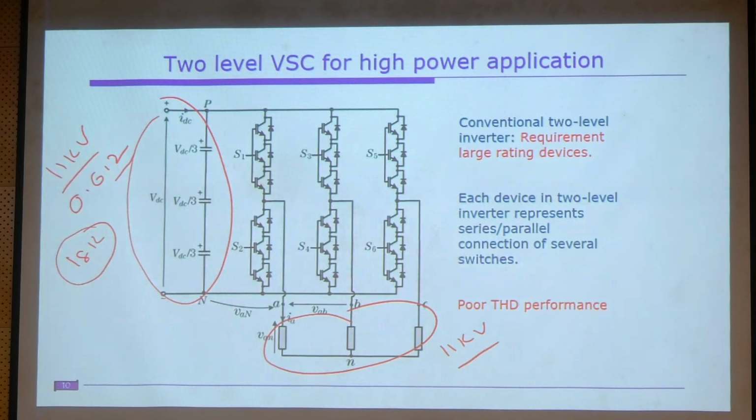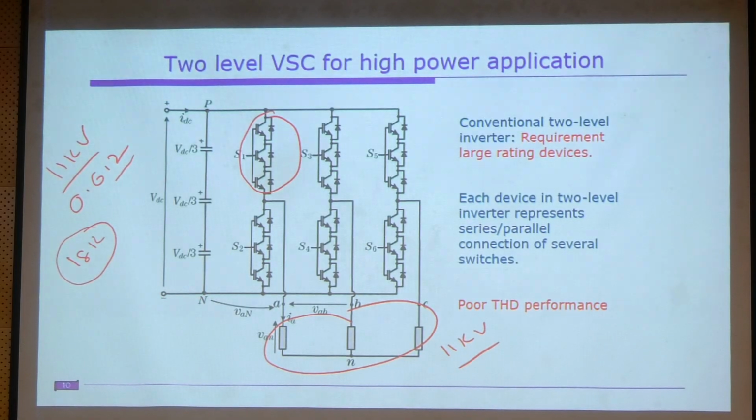For example, you have connected 3 devices here. The drawback is that if one device is faulty, the burden is supposed to be shared by the remaining 2 devices, right? That leads to the damage of the remaining 2 devices as well. Therefore, normally they slightly add 1 or 2 extra devices. Obviously it is a ship, so reliability is the biggest challenge for them. They will not worry about the cost and all those things. They will add whatever they think, maybe 10% or 20% extra devices.